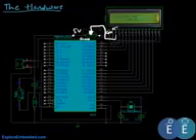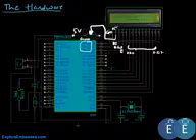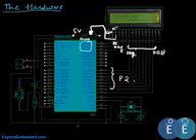Now next, this is called the register select, this is read write, and this is enable. So you should be pretty familiar with them now. From here to here, this will be your data bus, so this is data bus 0 to data bus 7. As you could see, register select, read write and enable are connected to port 0 in the example, and the data bus is connected to port 2. So 7 is connected to 7, so this is DB7 and this is DB0, sorry for that.